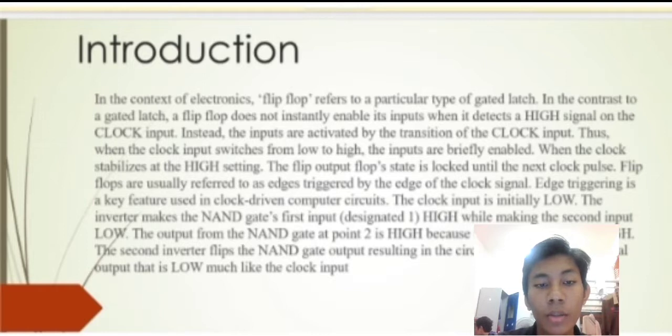And today, I would like to present about the introduction of our group project. In the context of electronics, a flip-flop refers to a particular type of gated latch. In contrast to a gated latch, a flip-flop does not instantly enable its input when it detects a high signal on the clock input. Instead, the inputs are activated by the transition of the clock input. Thus, when the clock input switches from low to high, the inputs are briefly enabled.